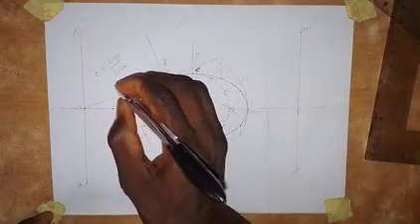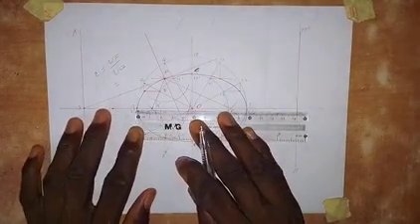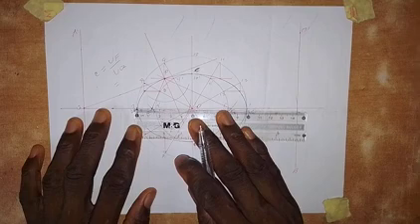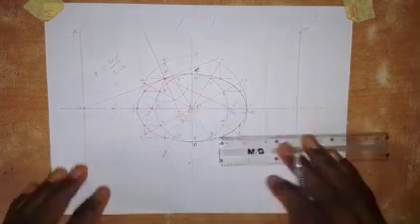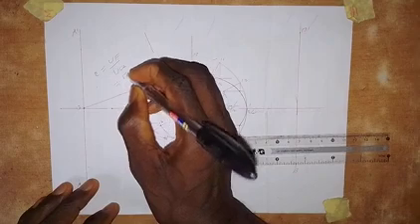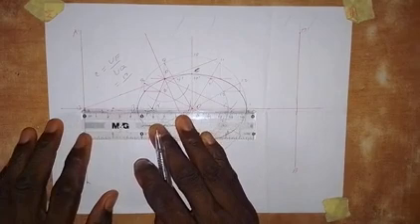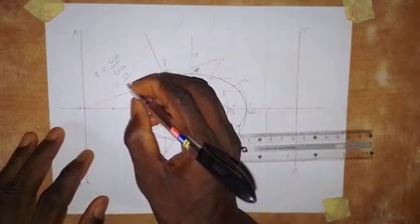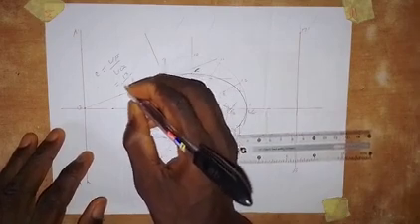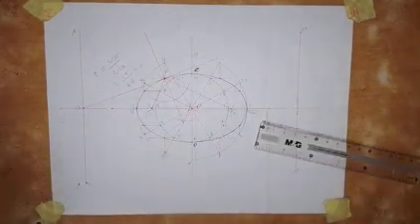If I take a measurement from V to F here, this is around 13 millimeters. So here I have 13. Over, if I take the distance of V from Q, this gives us something like 46. So we have 46 here. Whatever we get here is going to be 0 point something, which is the eccentricity of an ellipse.